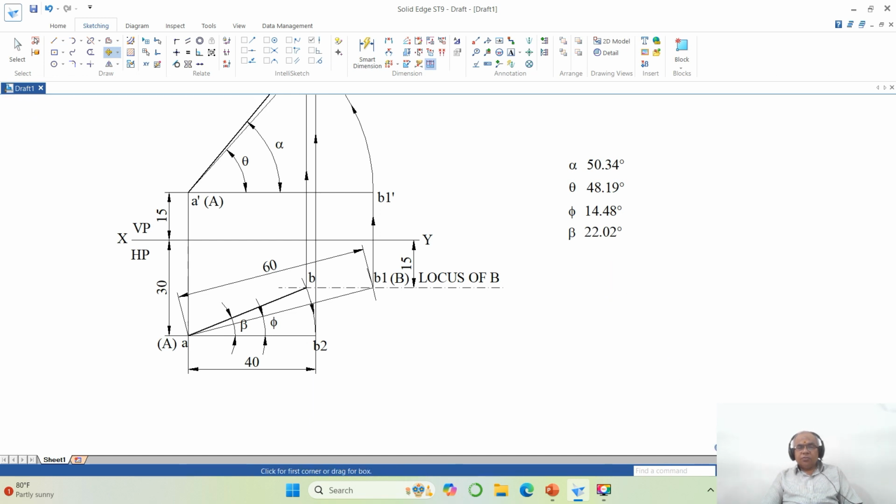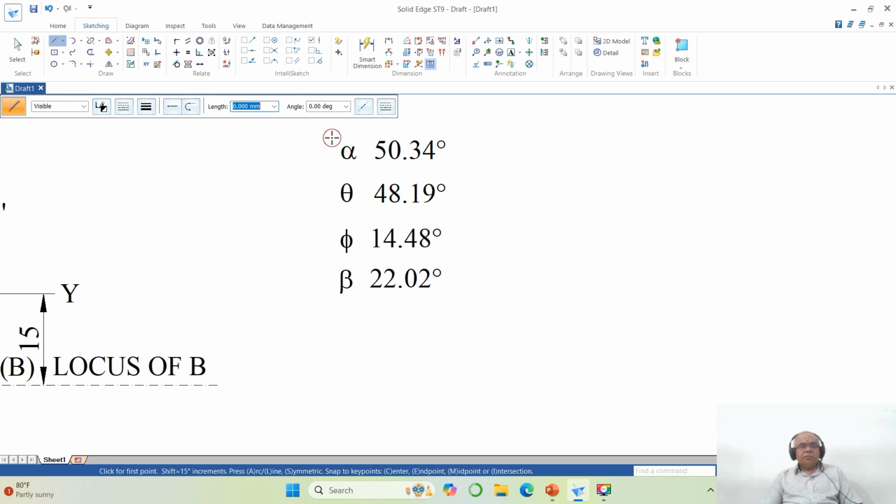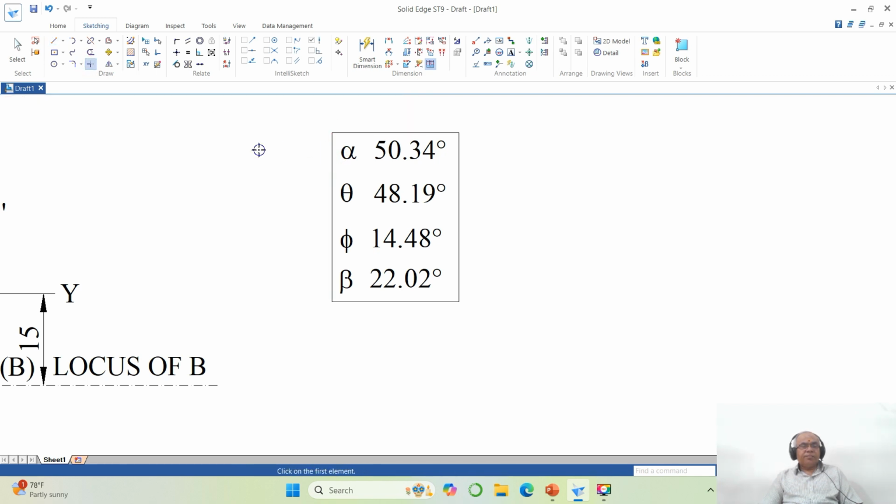Once you do that, then go to zoom window and go to line command, draw a vertical line, then I want to draw a horizontal line, then vertical, then go to trim corner between these two, then go to move, enable copy, select this, click somewhere. So I don't want to have the displacement along the y-axis, so make it 0. So you got this, then right click.